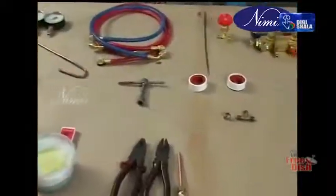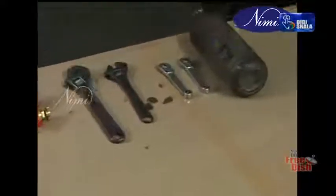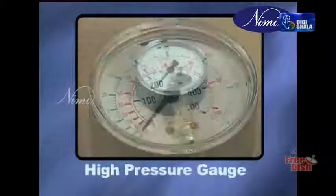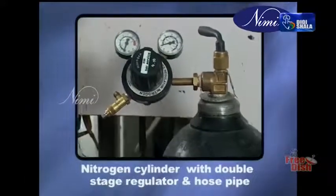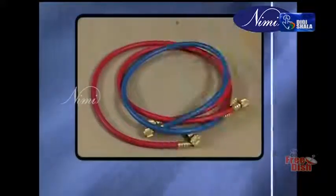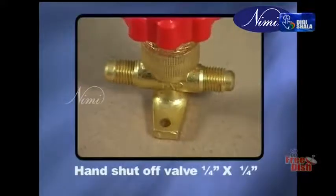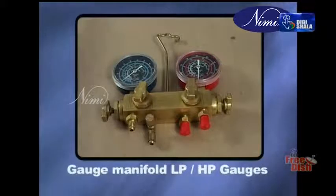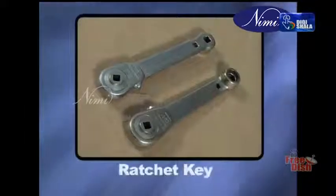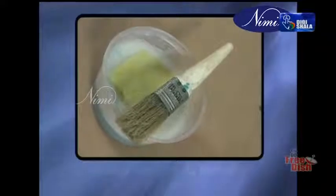To detect the leakage, the following tools and materials are required: high pressure gauge, nitrogen cylinder with double stage regulator and hose pipe, charging lines, brazing set, hand shut-off valve 1/4 by 1/4 inch, gauge manifold LP/HP gauges, adjustable spanner, ratchet key, refrigerant cylinder, soap water and brush.